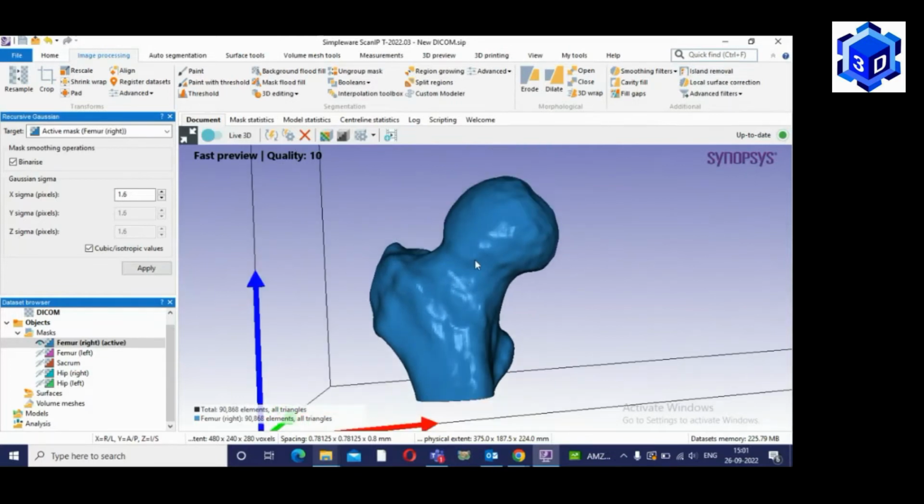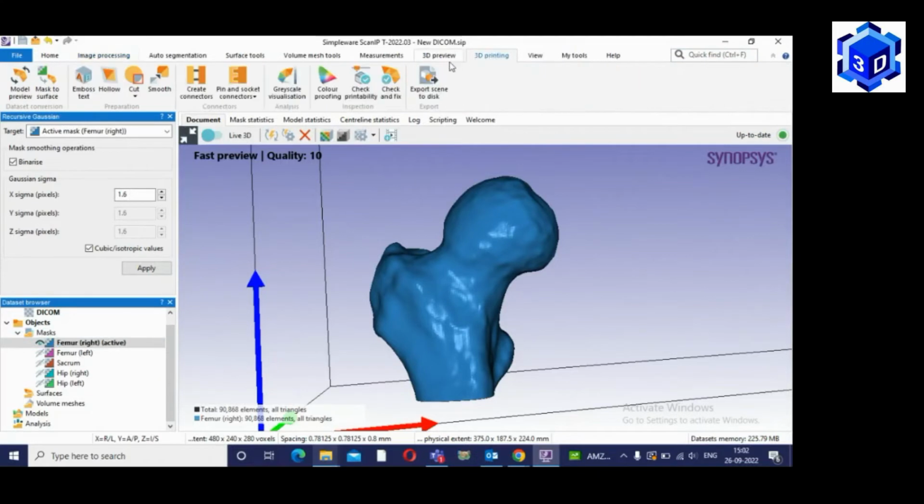I'll show you the 3D printing conversion or the STL file conversion from here, as we can have a model in our hand from the very ground zero, that is the import of our data, the scan data. I have segmented our data. I have done some morphological tools in that. I have split the regions as well. So now I'm going to have our structure, we have some more options from here. Yeah, this 3D printing option covers the mask to surface.